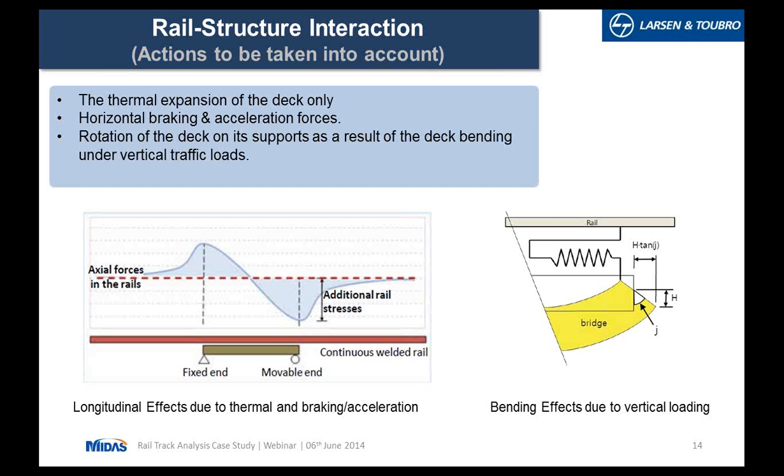The same phenomenon happens also in case of braking and acceleration, the only difference being that the forces are transmitted from the rail to the deck, which is opposite in case of thermal, where the forces are transmitted from the deck to the rail.